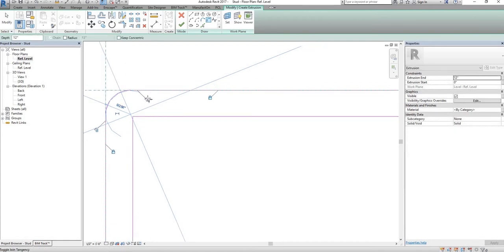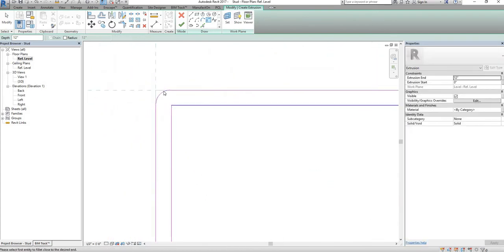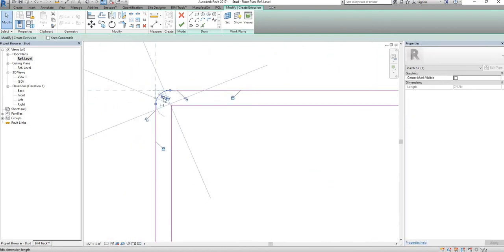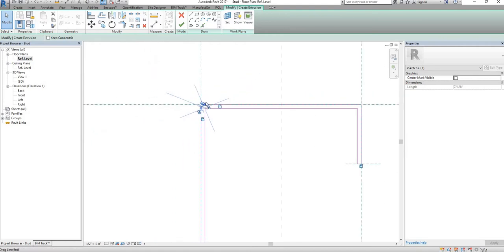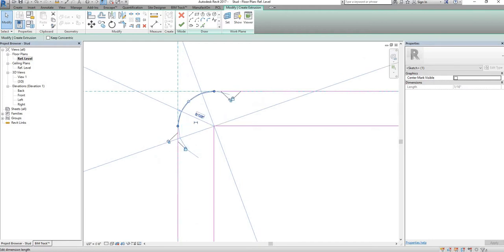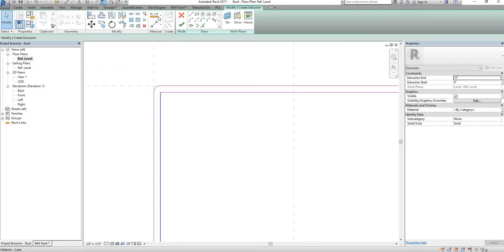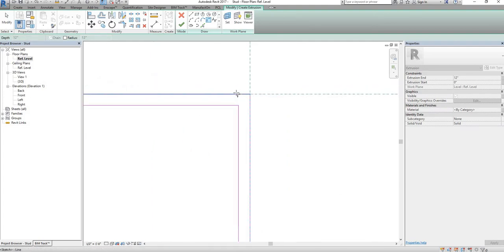So we want to make sure that we lock this tangent here, these two little tangent lines. If you don't lock them, you'll have issues. Stuff will just fly everywhere. So we'll make this 1 millimeter. And we'll do the same thing again. I'm actually just going to fillet these and then I'll come back and change the dimensions after.